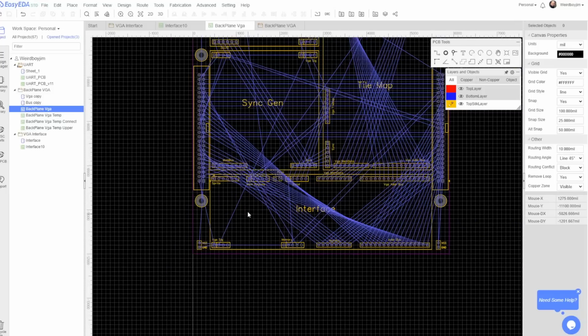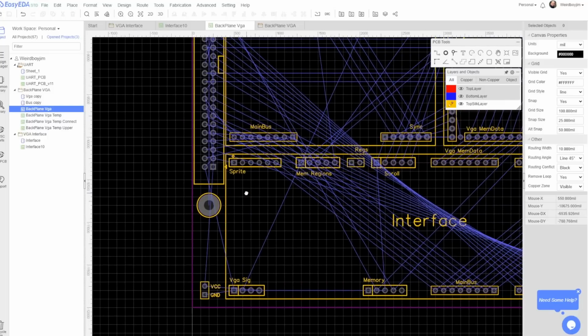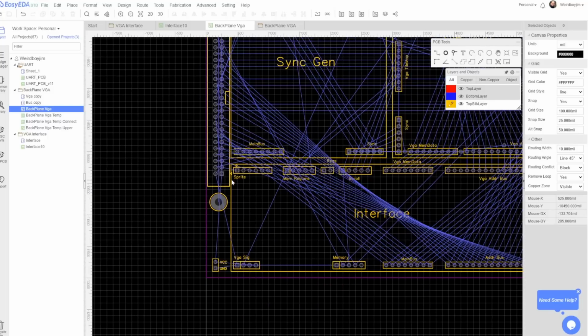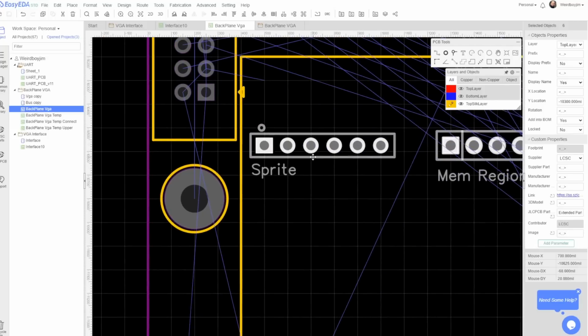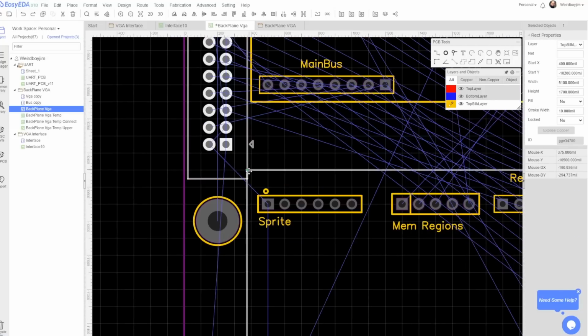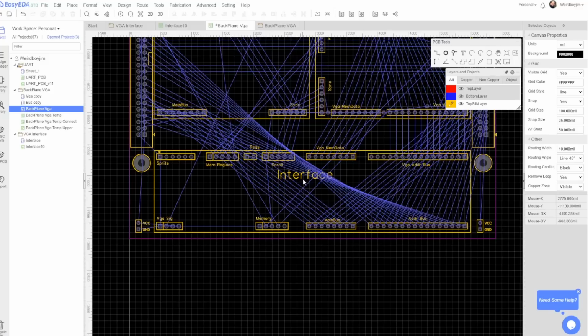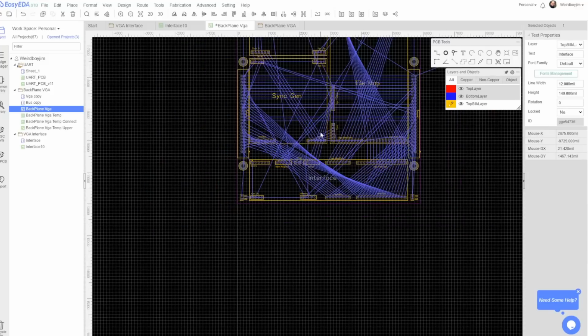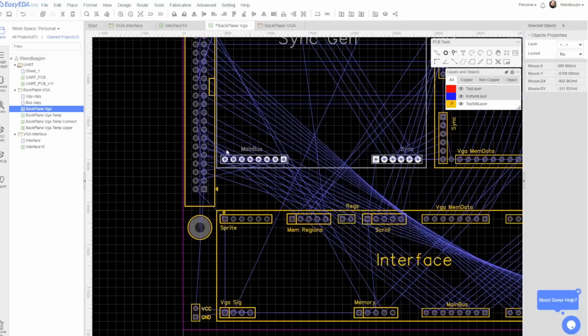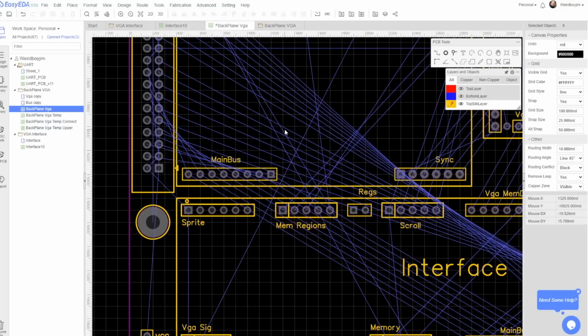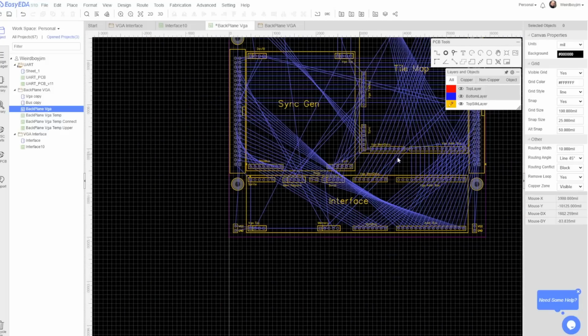When I did the I/O backplane, it was pretty tough to cross-connect the buses, and connectors in the middle like this made that difficult. So I'm thinking I can solve both these problems if I can make the interface board slightly shorter. If I can get these connectors down beneath here, my life will be much easier. Now it's quite a bit less space, but we were pretty comfortable on that PCB. It's going to give me the space to get over these big connectors.